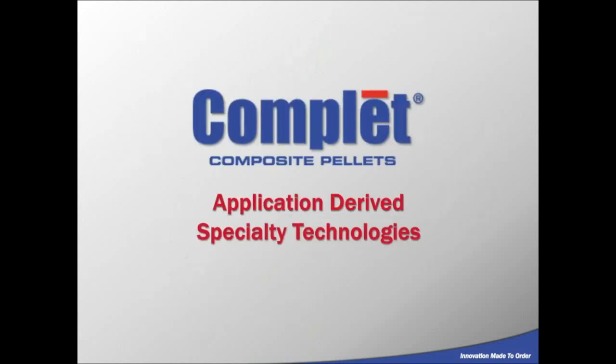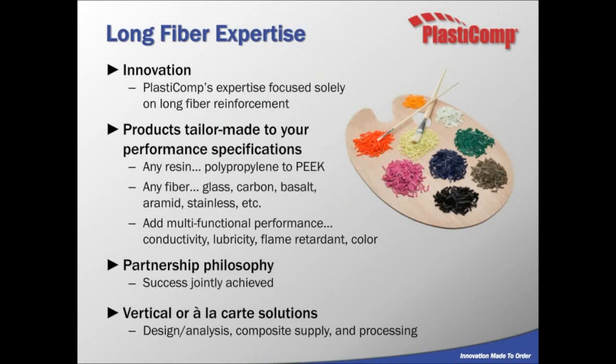Not only can we add reinforcements like glass and carbon to our long fiber materials, but we can also tailor them specific to your application by changing the base resin. They can be used in any base resin, from a commodity polypropylene or olefin up through engineering resins like nylon, TPUs, all the way up to very high performance resins like PEEK. Beyond glass and carbon, we also have basalt, aramid, and stainless steel fibers. And then we can add multifunctional performance with regards to lubricants. If you need high wear resistance, we can add PTFE and silicone, flame retardants, as well as color. And color would be specific to glass reinforced products.